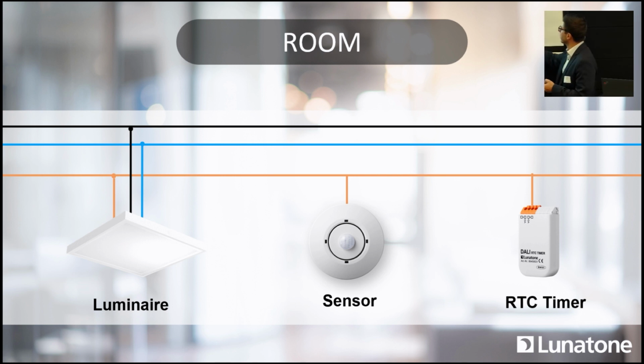In that device, you can control the light at a certain time. So you tell the device, okay, shut off all the lights, so arc power 0 or off would be the command. You configure it so that it sends this command at a certain time or a certain day. With the built-in clock, it knows exactly, okay, it's Wednesday, 7 o'clock. Let's shut off all the lights, or on, or 80%, so there are endless possibilities.